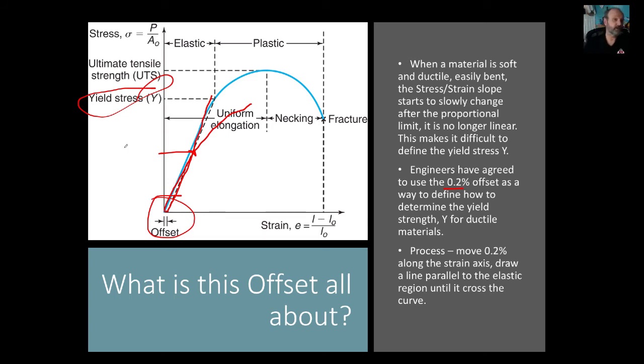And that's important when you're designing, right? You usually want to design down here in this region where it's linear, where it's elastic, because then if you design a part that way and you put some stress on it, it'll bend, but when you release the stress, it goes back to its original shape. So you typically want to design so that all of the forces and everything that your device will encounter is down here. It doesn't get much above this. If it goes all the way up to here, then you're going to get some permanent deformation in your part. So springs is a really good one, right? You want the springs to always come back to their original shape.